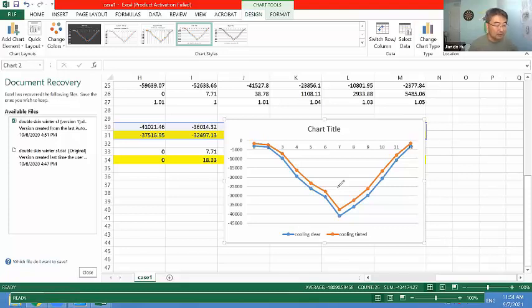Now you might ask at this point, how can you draw an overall conclusion based on this climate, based on one year? Should we do tinted or not, just for energy purposes? Typically, we would convert heating and cooling separately into dollars, into the bills that you have to pay. Because for heating, you might use natural gas, but for cooling, you'll probably use electricity. You really can't compare gas and electricity because they have different prices to give you the same effect. It's hard to compare that without converting all this energy requirement into dollars. So basically, calculate after a year how much money you pay between these two types of glazings.